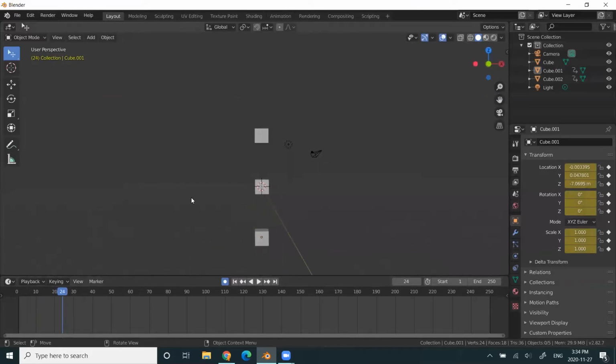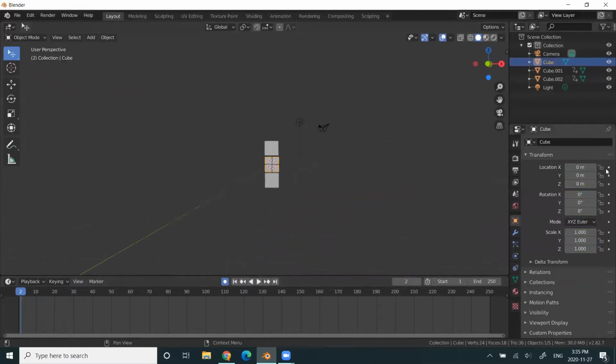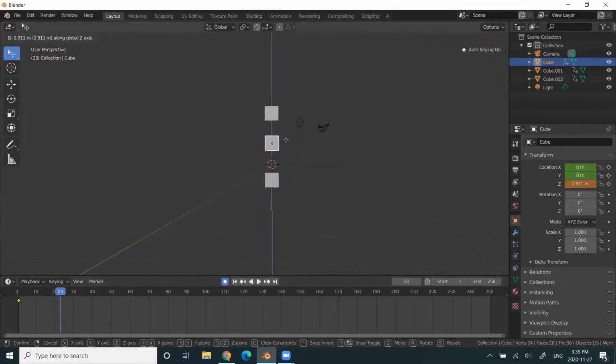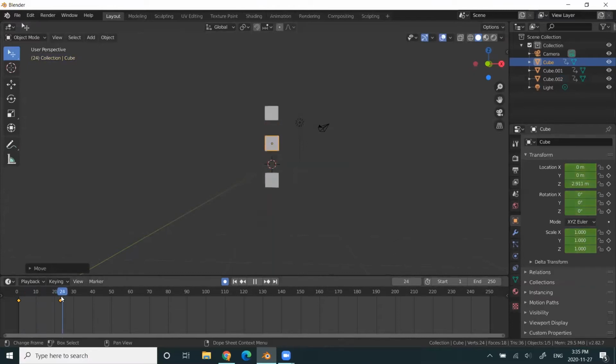And when you do the exploded view, I recommend picking one of the middle pieces and then pulling out the rest of the parts outwards from that origin. It obviously depends on the object that you're doing. And you don't have to do it from the middle and outwards. Let's say it was a stacked object like this, and maybe I want to actually move this from the bottom. So if this one is being keyed here, I can move this at 1. At 24, I can move this object up here. So now you'll see it moves from the top. So however you do it, it's all up to you. You have the creative control to do whatever you think is clear to show the exploded view.